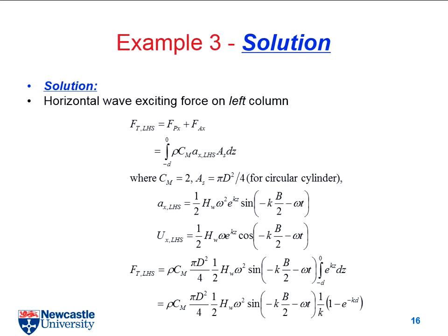So that's the reason why you can see the calculations in the following two pages. The first one page is for the force on the left one, and you can see that it's integration. And we need the cross-sectional area is here. And we need the depth of that small element, and we need to do the integration. We need the density, the coefficient for added mass. And then here is the acceleration. And you can get this acceleration from your table. It's here. Right? And then you can have a final expression.